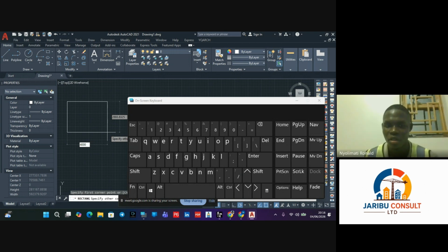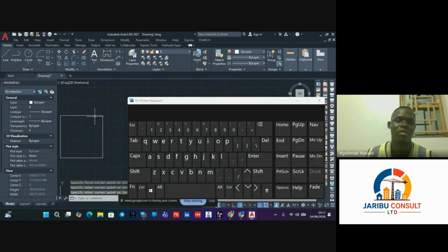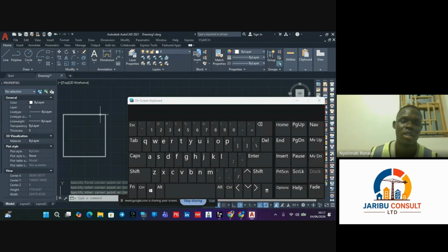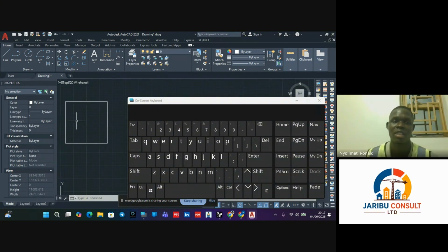After writing 4,000, I will not click anything. I come here, I click on tab. Then I write another value, maybe 4,000. And then after that, I click enter. You see, it has done it for me. You have seen something like that? Yes, it's as simple as that. That's how you draw the rectangle. You close this.